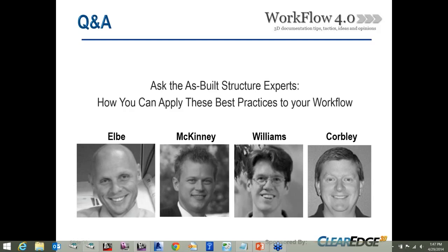And Kevin Williams, how deformed can structural steel be and still facilitate fit to cloud? Not terribly deformed. If you've really got a twisting I-beam, it's going to have some problems with that. What I've recommended to a couple of our beta testers who've been modeling pretty significantly deformed steel is that they model it in sections and then connect those sections together.